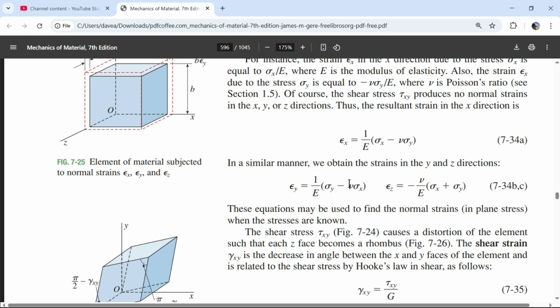That's the hardest thing about textbooks: in just one little sentence and then a little equation, you can kind of lose exactly what they did. And that's a point where you would want to combine these two equations and solve for them. But it's also a good habit to be able to do that mentally, any way possible. That's why I said, hey, I could solve for sigma x, get everything to the other side. I would have a strain x and sigma y. I can shove it into here. I would for sure have sigma y's. I could combine those, and then just get the sigma y by itself, and I would have strain in the x, strain in the y. So that equation will have strain in the x and strain in the y, and that'll be our first one.